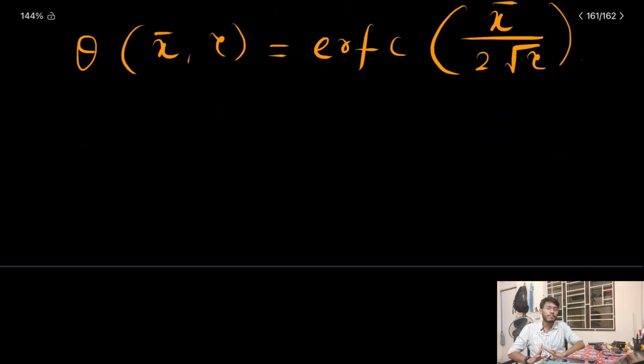Now there are some important things. If you change the boundary condition, in the previous approach, in the approximate solution, I have done it with the constant wall temperature, I mean if I put a heater that will maintain the temperature at x equal to 0 for any time greater than 0, and also I solved the same problem with the approximate approach with a given flux that is maintained at x equal to 0 for any time t greater than 0.